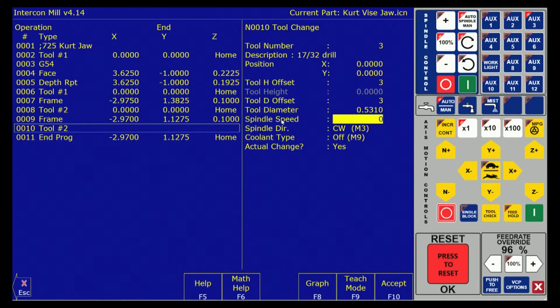In this rigid of a setup that we are going to have, we don't need to spot drill for the purpose of locating a hole. The reason we spot drill primarily in the CNC world is to create a lead-in chamfer. So we are going to put a 1/4-20 thread in the side of this part. We will spot drill there to get a lead-in chamfer. We'll also do it to have an edge break at the top of a tool.